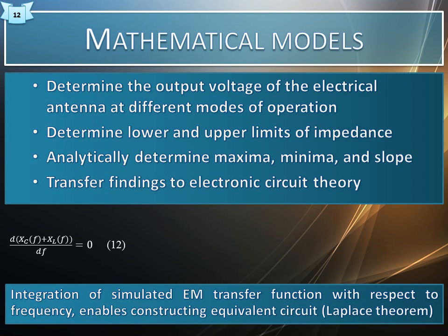In order to determine an equivalent circuit for the radiating antenna, taking into consideration the high-frequency substrate and parasitic effects, and not considering first-order equivalent circuits available in the current body of knowledge, an analytical approach was taken to convert the transfer characteristics from a fully operational dipole antenna on a substrate to an equivalent electronic circuit. The resulting transfer function and circuit points at a circuit that is mathematically cumbersome to solve, and this method speeds up the process significantly by estimating a possible circuit where addition of a Monte Carlo analysis can further improve the accuracy of the results.